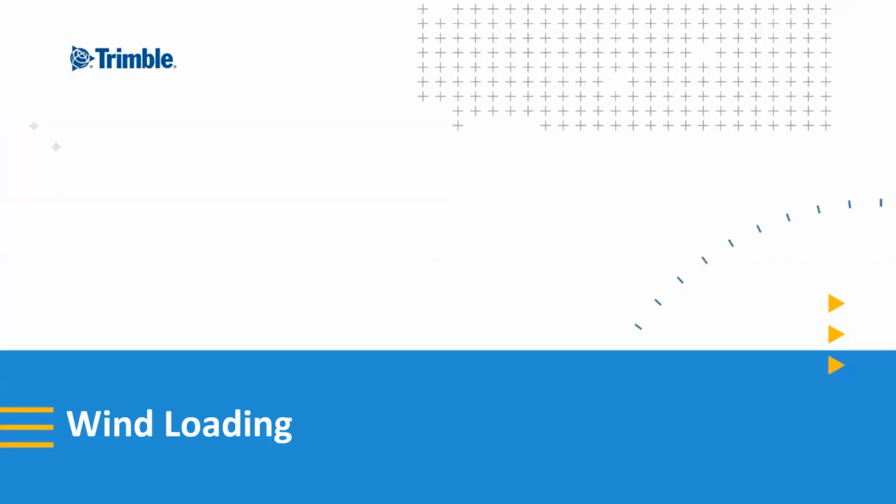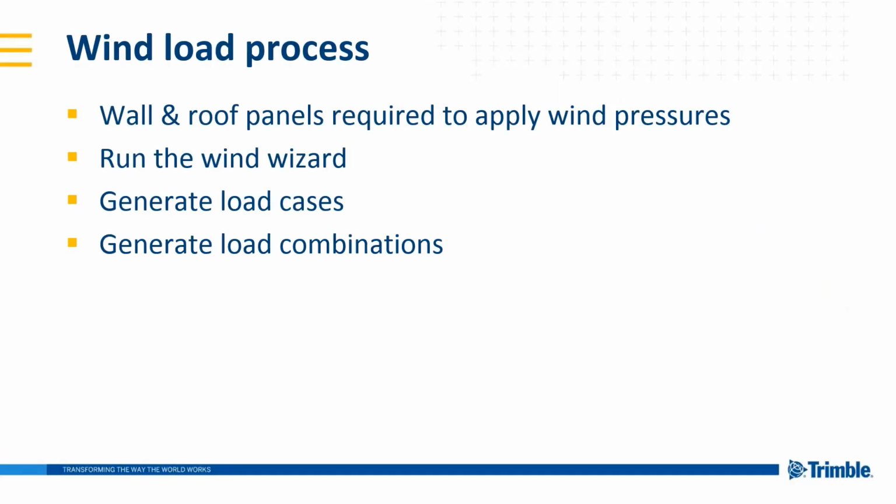Now let's take a look at the wind loading in TSD. In order to have the program calculate your wind loads, you must first apply wall and roof panels around the exterior of the building. These are distribution areas and they tell the program where to place the wind load. They are required even if you have concrete walls on the exterior.